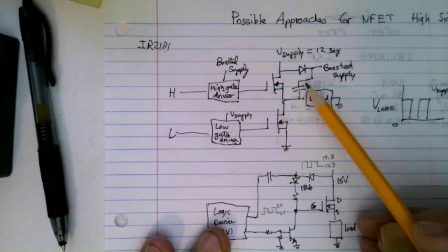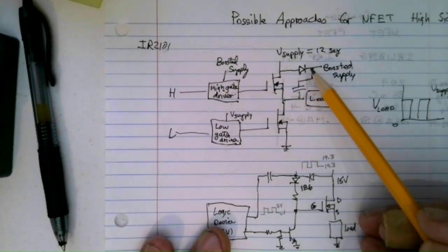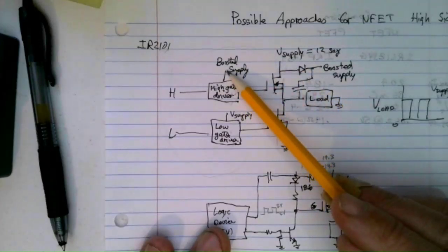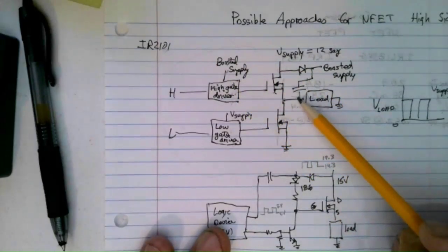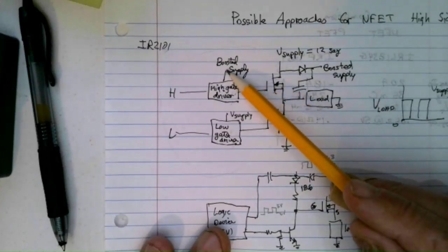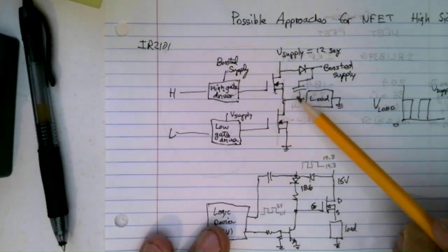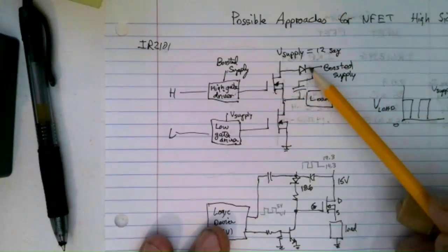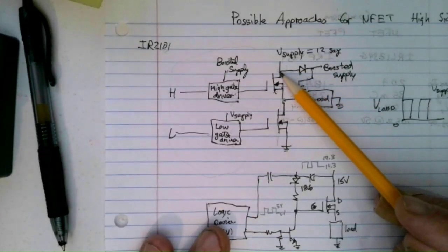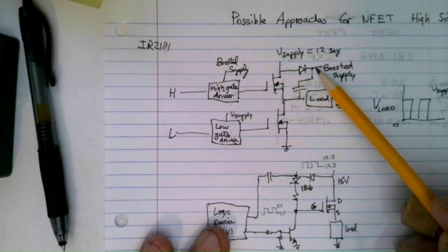And as soon as this voltage starts to increase, this diode shuts off, and you'll see this voltage increase in lockstep with this voltage, and that provides the extra gate voltage to get this part to turn all the way on. That's what they call a bootstrap configuration, and it really is just a half-wave rectifier. The only thing is, the half-wave rectifier is not referenced to ground, it's referenced to whatever the supply is. So this voltage will be higher than the supply. In fact, it would be about 23 volts.